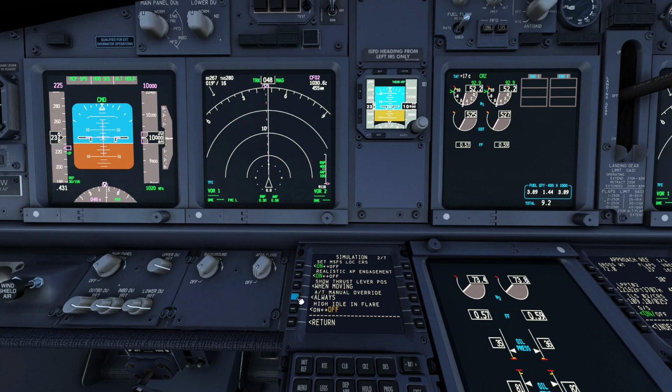I do like the mode throttle hold or descent arm only, because in this case, anytime you have an active auto throttle mode here that is not throttle hold during the takeoff and descent arm during the descent, you can move your thrust lever, the physical one, as much as you want.